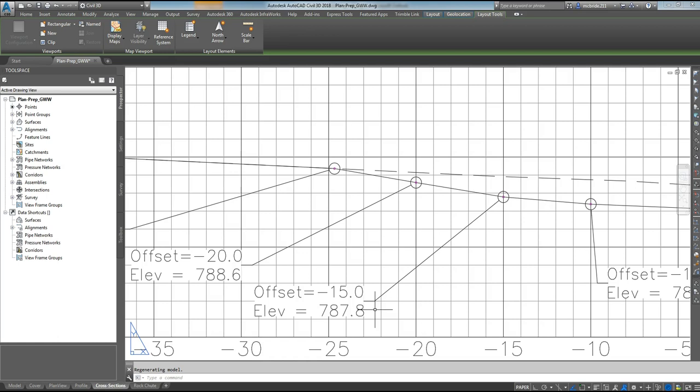accurate to at any one point, because if you put your survey rod in one spot, it could be a certain elevation. If you put it right next to that one spot, it shouldn't change, but because of the clumps of the dirt and things like that, it could go down a few hundredths of a foot. So that's why we're only staying accurate to within a 1/10 of a foot. But you can see here at 15 feet from the center line, my elevation should be 787.8. If it's 787.9 or 786.3, I'll know that it's off by so much, and I can inform the contractor that they've got to come and address that.